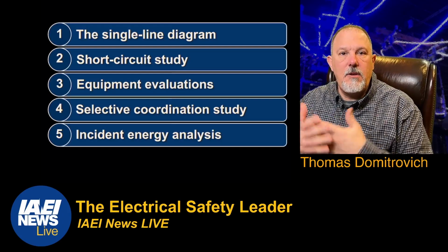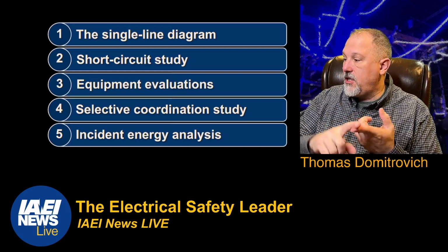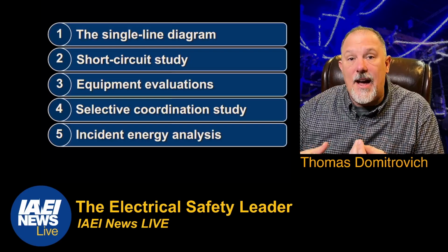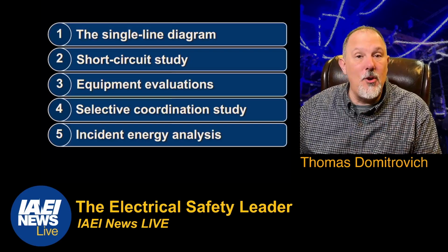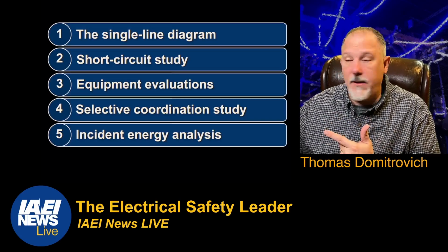Short circuit study, you need to make sure that that's critical for equipment evaluations, for selective coordination, and incident energy. You can't do 3, 4, and 5 if you don't know what your fault currents are in your power distribution system. So get on it.